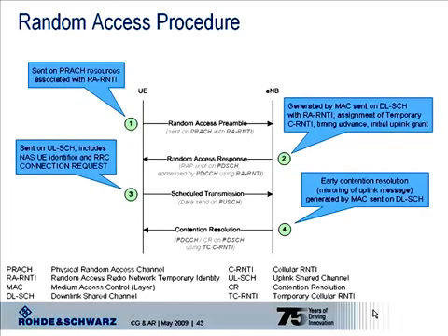6 adjacent resource blocks out of the available bandwidth are occupied by the preamble, but where these resource blocks are located is configured by higher layers via the system information. Based on information derived from system information block type 2, the UE also knows in which subframe a specific one or all in that radio frame the preamble can be transmitted and which preamble format is to be used. Altogether there are 5 formats, where the first 4 are applicable for LTE FDD and LTE TDD, and the 5th one just for LTE TDD. The different formats are necessary to bridge the gap between the base station and the UE.